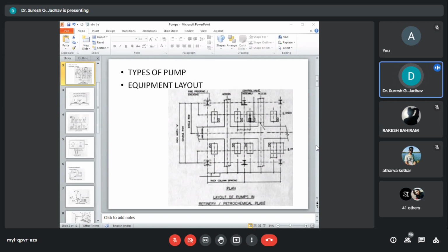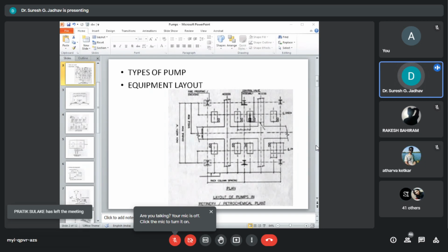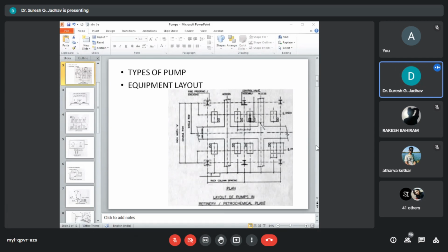Suction piping should be short and straight with one or two expansion joints. Inline pumps are compact and mounted along with pipelines, even overhead. Larger inline pumps may need separate support on vertical shafts. Pumps occupy less area but need headroom for removal.